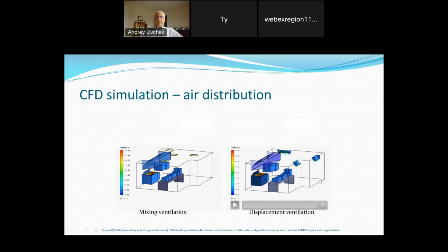The floor space in kitchen is at a premium, and we've placed displacement diffusers near the ceiling here, but still it provides displacement effect because cold air cascades from this displacement diffuser towards the floor, then spreads in the occupied zone and is carried in the upper part with heat producing cooking equipment. Again, let's take a look at air movement in the space.